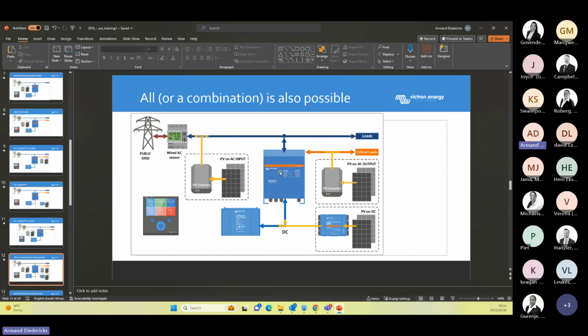All right, so bear in mind the AC coupled systems, 1-to-1 ratio. And yeah, don't overpopulate the inverter to produce more power than the hybrid inverter can carry. Right, any questions? Nothing. Everybody comfortable?